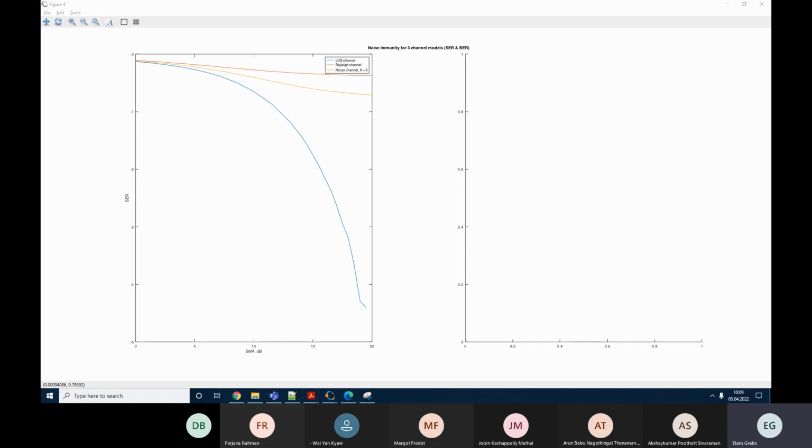We already discussed that in the lecture, if you remember, that this fading actually prevents us from reaching good signal to noise ratio, that it has some plateau effect that it will not improve. And in fact, we already tested that in the first section of our practical work, that even without noise, we still have very high error probability. So no signal strength can improve situation at all. It can even become worse for some signal to noise ratio, but eventually at some SNR value, we are reaching some saturated level, some plateau, and cannot really change much.